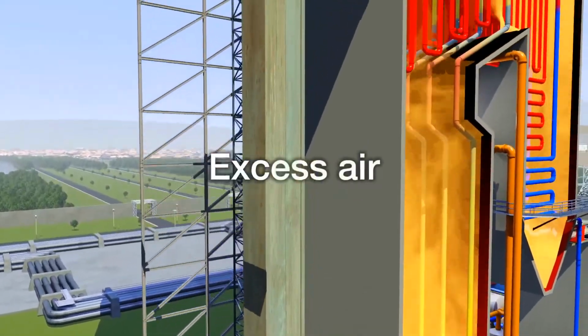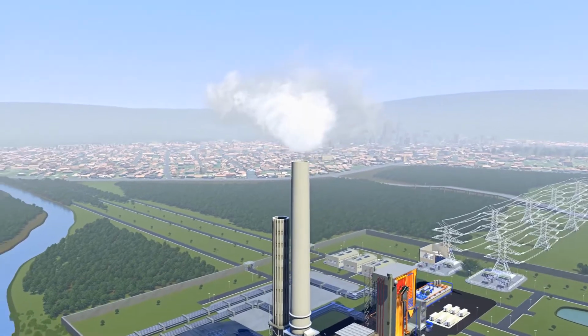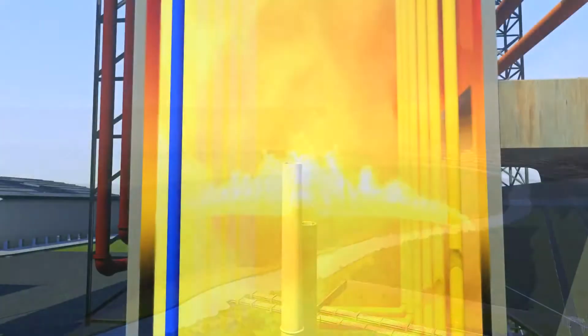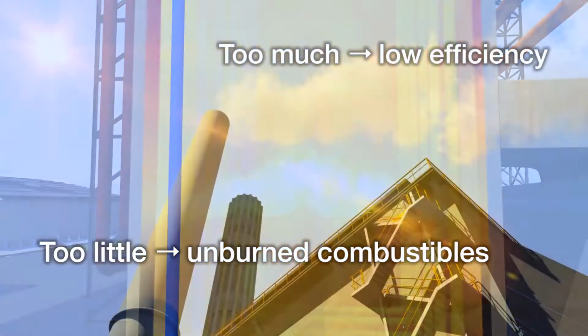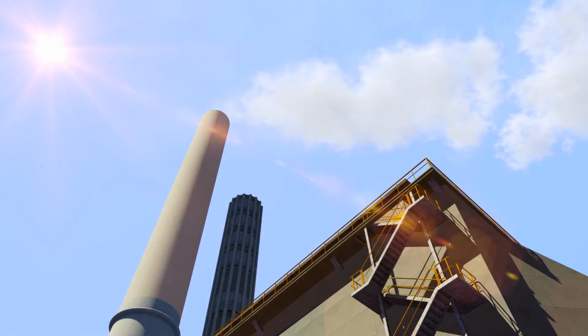The answer is to use a supply of excess air to help ensure there is sufficient oxygen to completely combust the fuel. Achieving the right mix requires a careful balancing act to ensure the right amount of air is supplied at all times. Whilst too little air will produce unburned combustibles, too much air will reduce combustion efficiency, with heat being lost via the stack as hot flue gases.